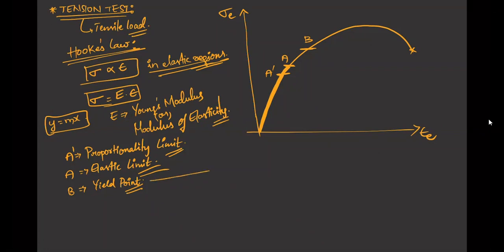How we have assumed the yield point is that there should be some minimum amount of permanent strain in the body, about 0.2 percent. That means if you draw an offset, which is a line parallel to the elastic line, I am loading my body, crossing the elastic limit, going over, and if I unload somewhere here at B, it should follow this path and retain a strain of at least 0.2 percent.